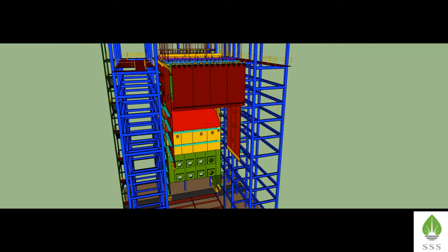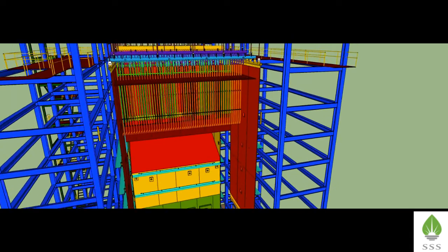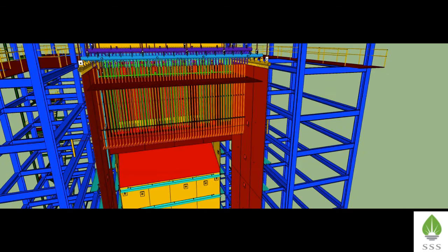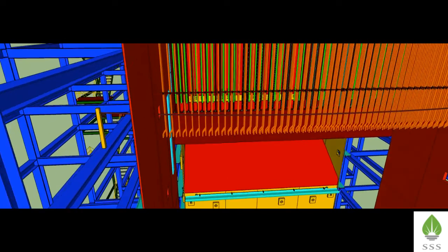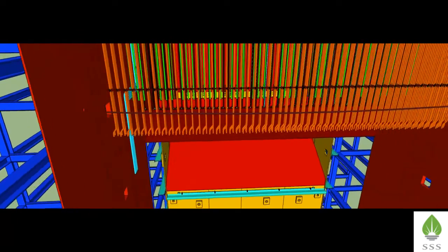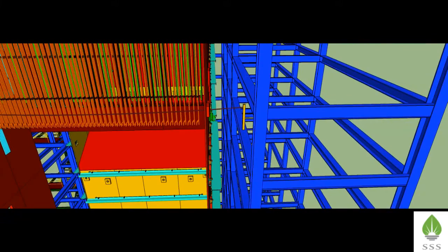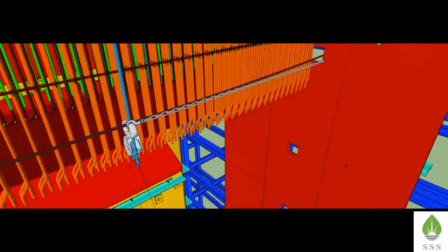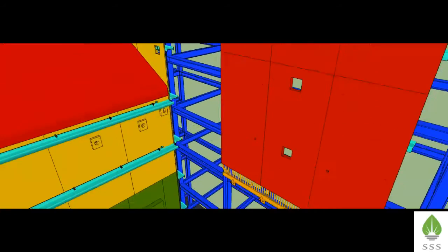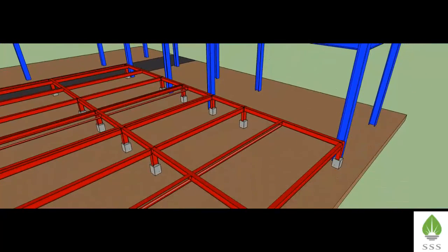In order for clear understanding of the lifting arrangement, the cage rear wall panel is hidden. For erection of primary superheater coils, we need to make the following lifting arrangement. A wire rope is tied between 2 supports welded on the boiler structure on both sides of cage wall panel. A pulley is suspended over these ropes. Lift the coil with this lifting arrangement.